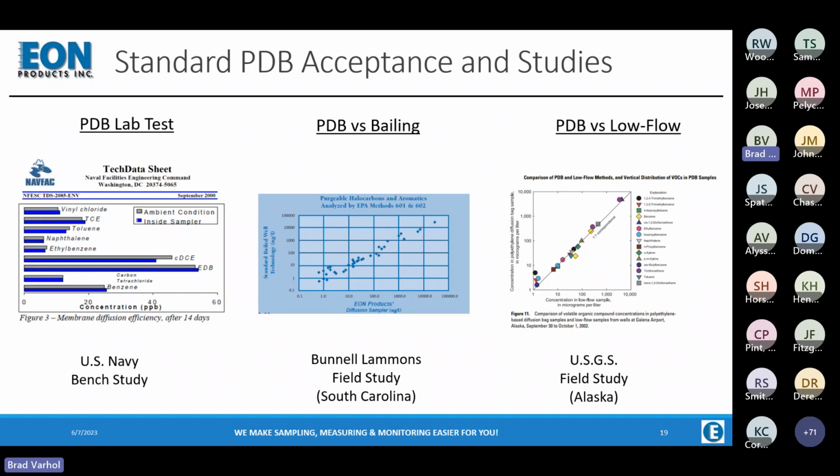Now, standard PDBs have been evaluated early on in their career, back in the early 2000s. The Navy conducted some testing in-house where they created a bench test with a test chamber that they spiked with certain VOC compounds of interest. They put PDB samplers into that spiked chamber. They let them have their residence time. They pulled them out and they analyzed the concentrations in the samplers and compared that to the concentration in the chamber that they used as their controls.